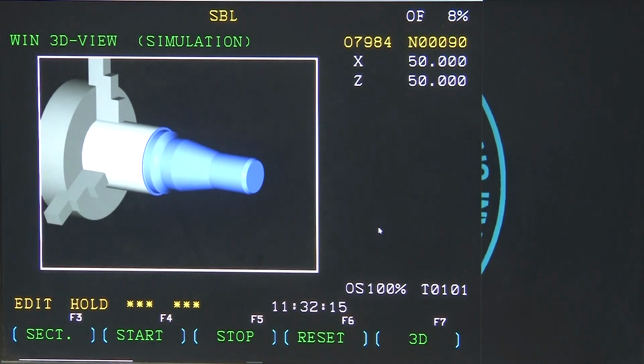There will be a few passes of rough turning, and the final pass will be finish turning, and the entire part will be made. So, that is as far as the turning of the cylindrical surface, conical taper surface, and so on is concerned. Next is the operation where, according to this drawing, you have to make the groove.